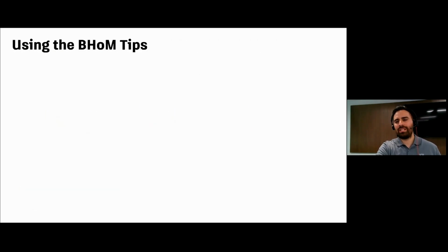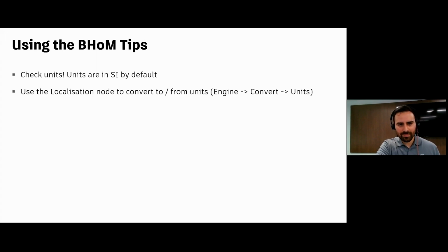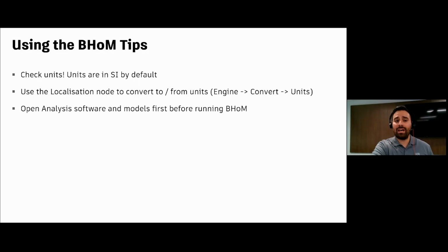All right, just some quick tips here on using BHoM. Again, check your units. I've made several mistakes thinking everything's in what I use in the US. They are in imperial units. I would recommend using the localization notes. So there's a way you can actually convert things. So if you want to go to meters or from meters or to feet, there's lots of information out there for it. I would always have the analytical software open before you run it.